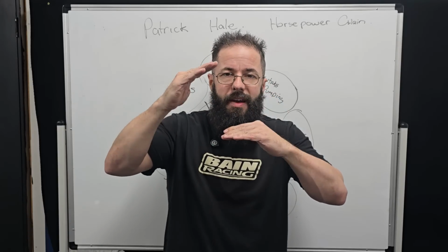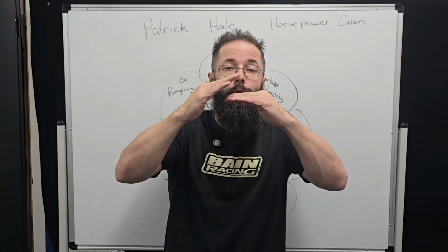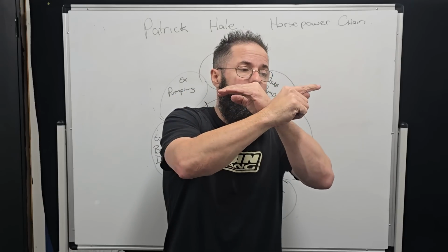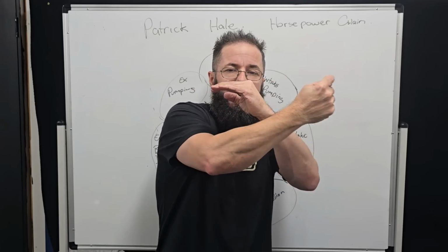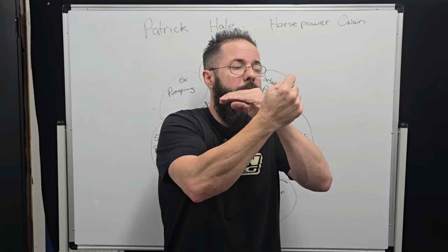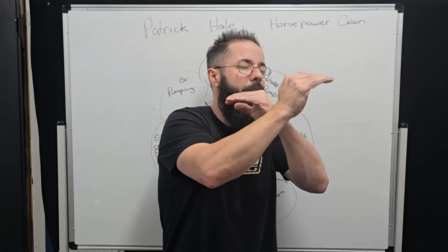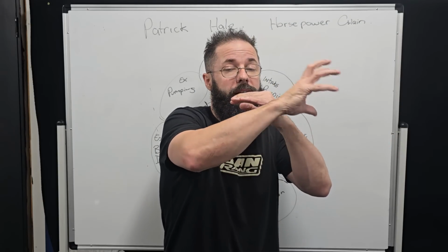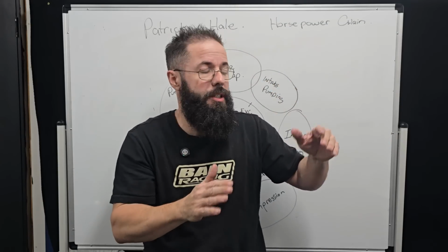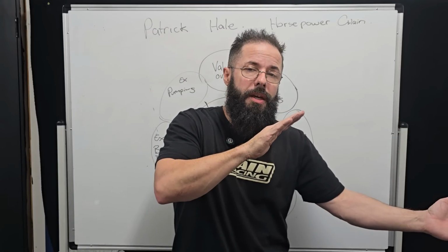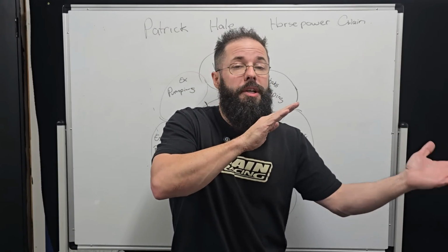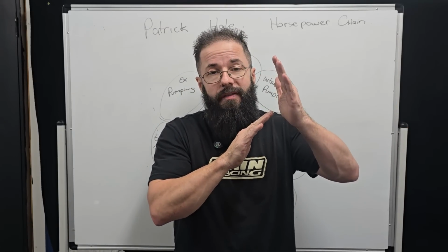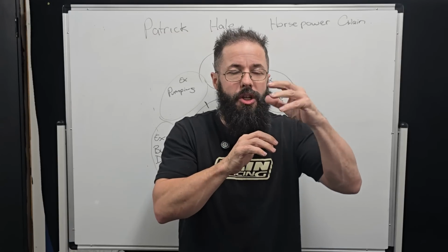So the instant that valve opens, even though the piston's still coming up, the exhaust valve should be in its negative phase. So it's now creating a negative pressure because the velocity is starting to fall. This is creating a suction on the induction system. And also, if we've tuned the pipe size right, then it's also sending a rarefaction wave in, a negative wave into the chamber.